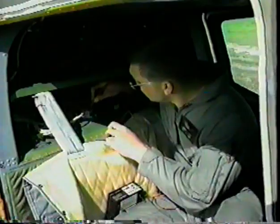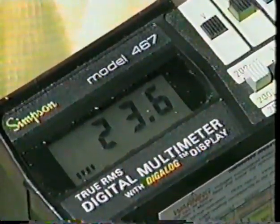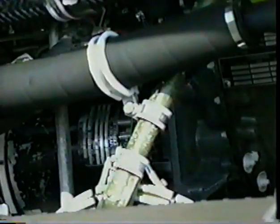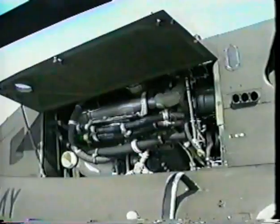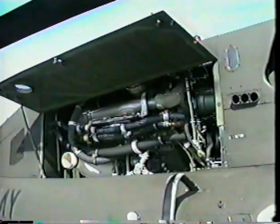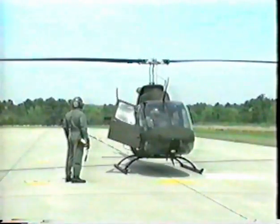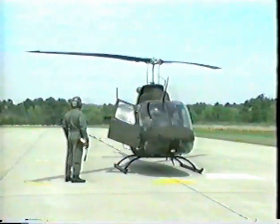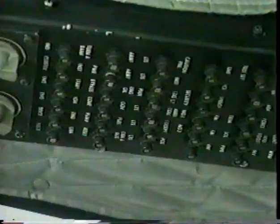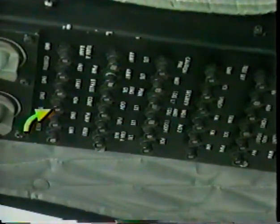Now that power is on board the aircraft, you need to start the engine. To do this, you would use the combination type starter generator, located on the underside of the engine to the right of the aircraft's center line. In addition to starting the engine, the starter generator is used to charge the battery and supply power to all DC electrical components. To start this cycle, begin at the overhead console essential bus and find the igniter circuit breaker.